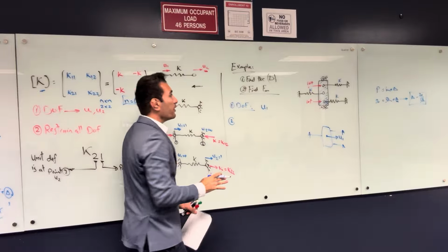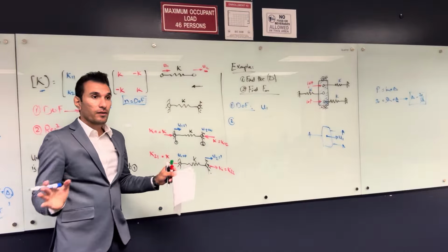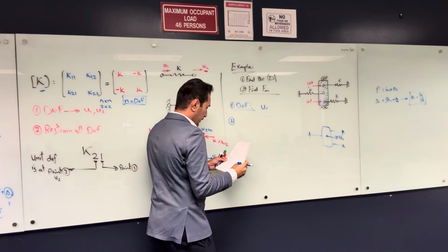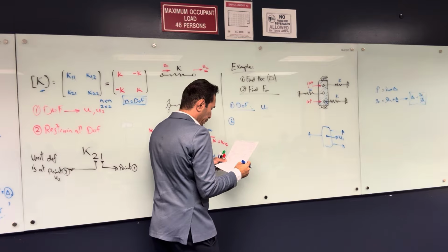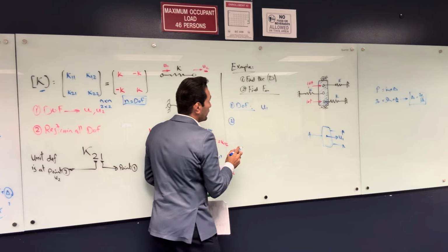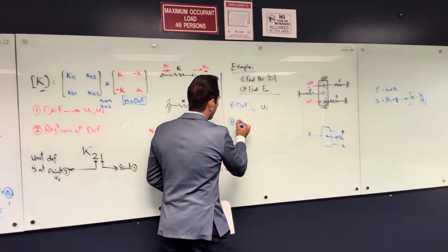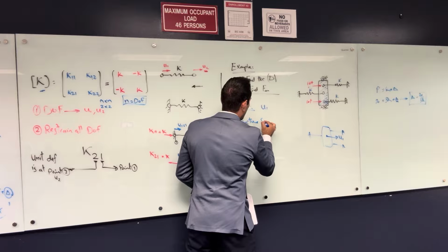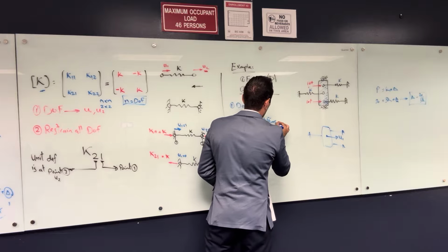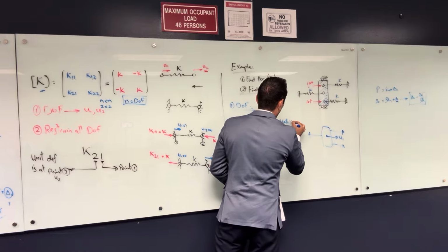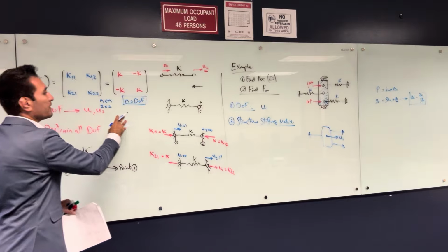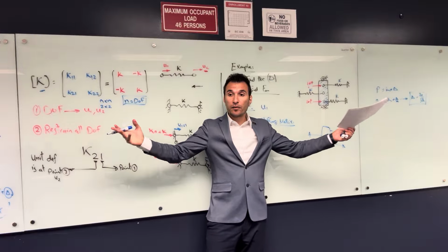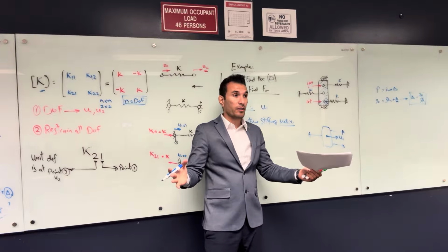Number 2, I want to build the structural stiffness matrix. Okay, I'm gonna make the node, because this is a nodal force. We're gonna talk about the nodal force in a little bit. So let's say structure stiffness matrix. I talked here about an element stiffness matrix, but I'm gonna tell you how SAP2000 collects the stiffness matrix of the element and makes the structural stiffness matrix.